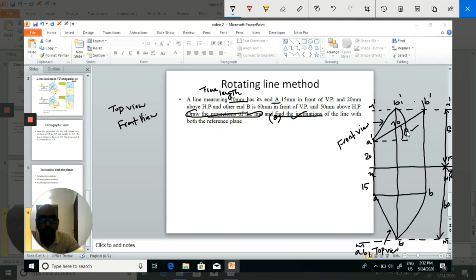The arc should meet the horizontal line from A dash. Let this point be B2 dash. Now from B2 dash draw a straight line vertically downward. It will meet the locus line M. Let that point be P2.